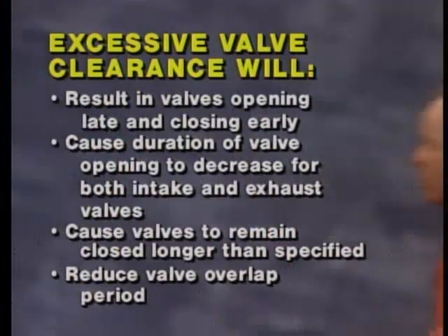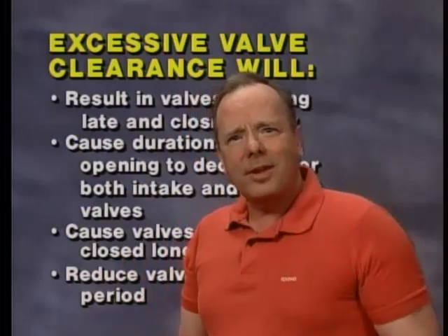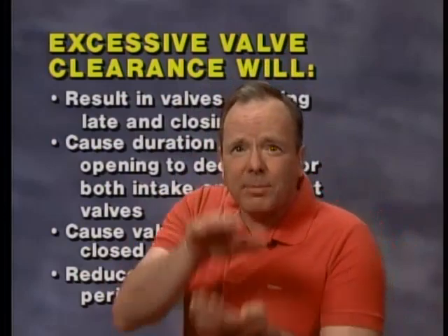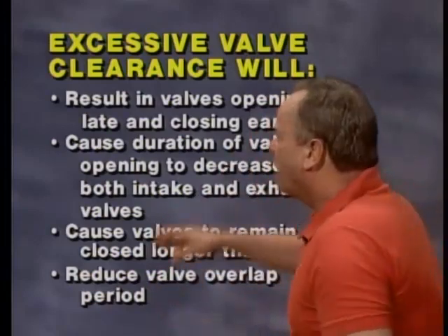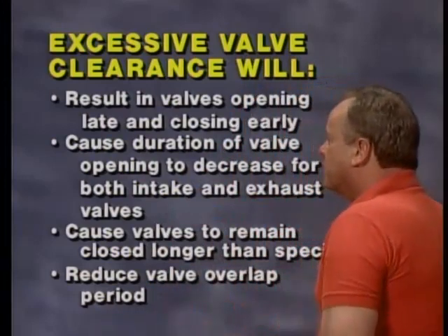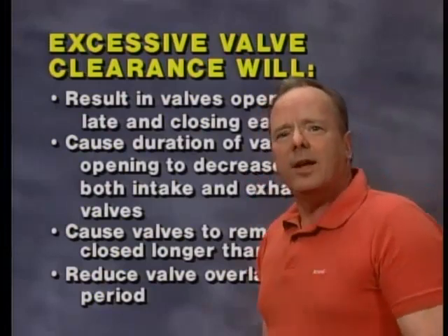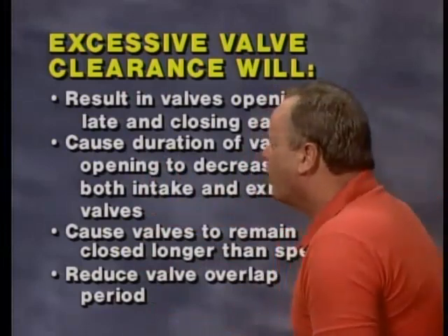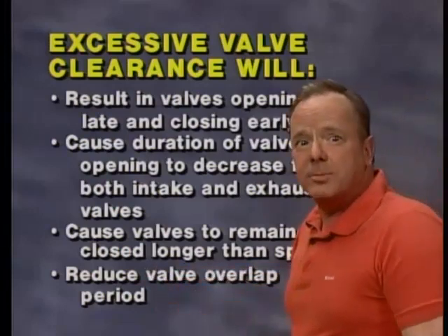Now let's assume that you adjust the valves on an engine and you have too much clearance. That's a bad thing because there'll be too much play in the valves, and you have to take up that play before anything happens. So that's going to result in the valves opening late and closing early. That tells you the valve isn't going to be open as much, so it's going to cause the duration of valve opening to decrease. It's going to happen for both the intake and exhaust valves. So the valves are going to be open less, and therefore closed more. The valves will remain closed longer than maybe specified by the engine manufacturer.